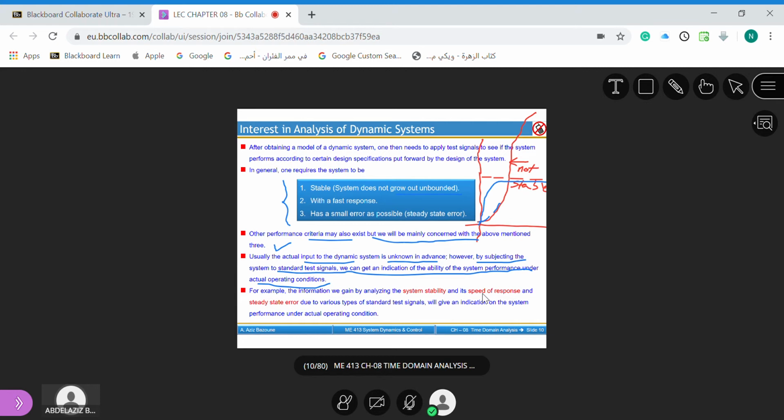The second order system has a certain behavior. Suppose you bought a device and you don't know whether it is a first order system or a second order system. To know the system of your device, you just plug in some unknown signals, like the step input or the impulse input. Specifically, the step input is the most used one because it has a drastic characteristic. It jumps from 0 to one value. So here we use this one.